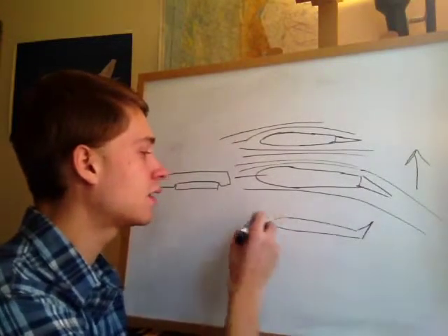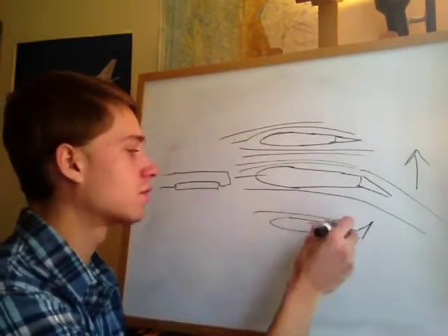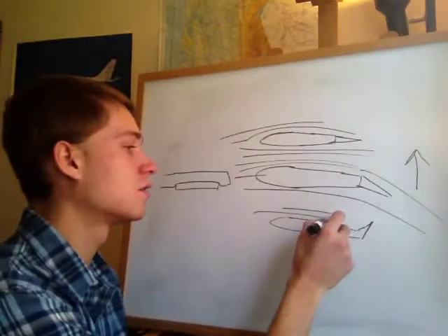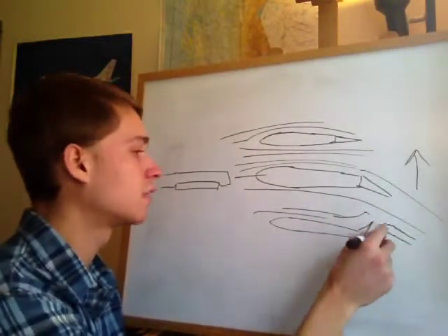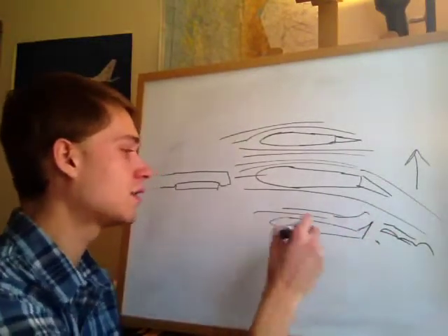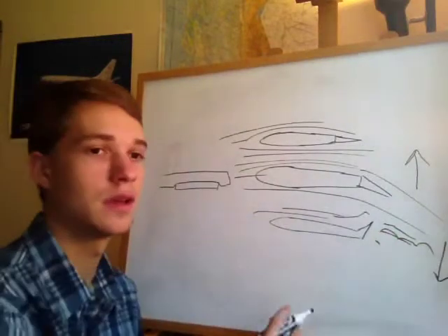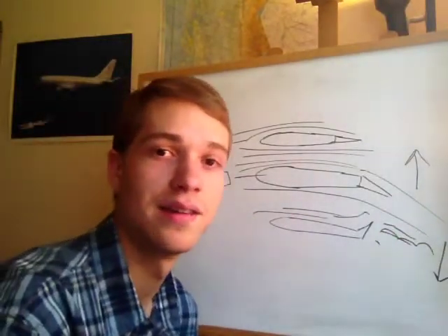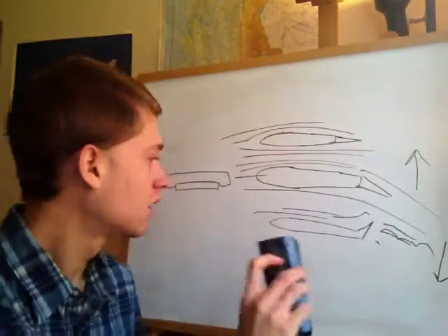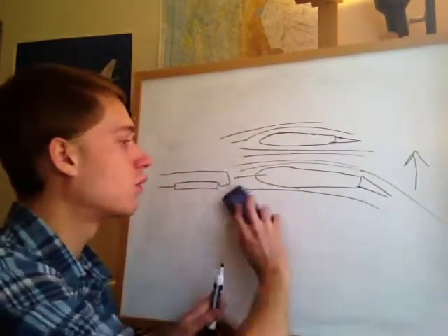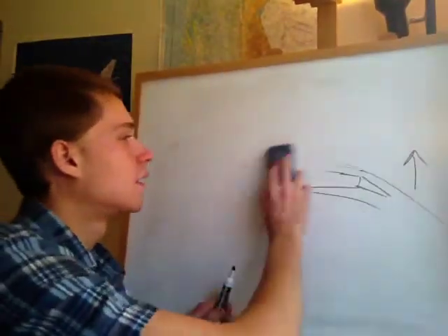So if you raise the aileron, now you're kind of producing resistance on the top, and you're kind of destroying some of the lift. And so in that case, the wing or the surface is going to want to fly downwards. So let's take a look at this when we want to roll our airplane into a turn.